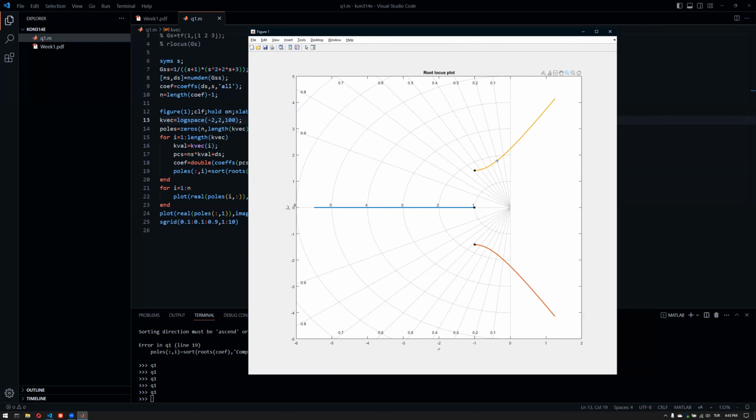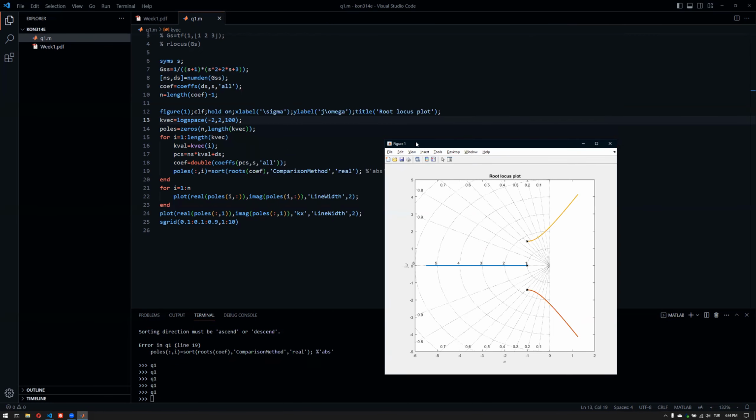For example, this point here, or even this one here, can be characterized with damping ratio 0.1 and natural frequency 2. So if we use 0.1 and 2 as values for damping ratio and natural frequency, you will end up with this pole pair here with its conjugate pair. And that's going to be important for the upcoming weeks.